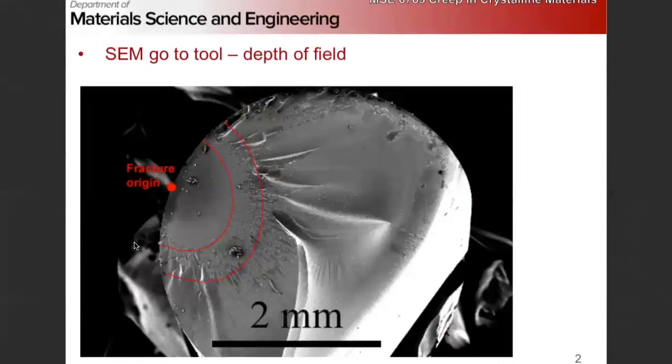It's something that people don't do anymore, is make replicas. Basically, there are a couple different techniques, but you can make a cast of your surface, right? And then put a carbon film on the negative of your surface, and then dissolve away your casting material, right?